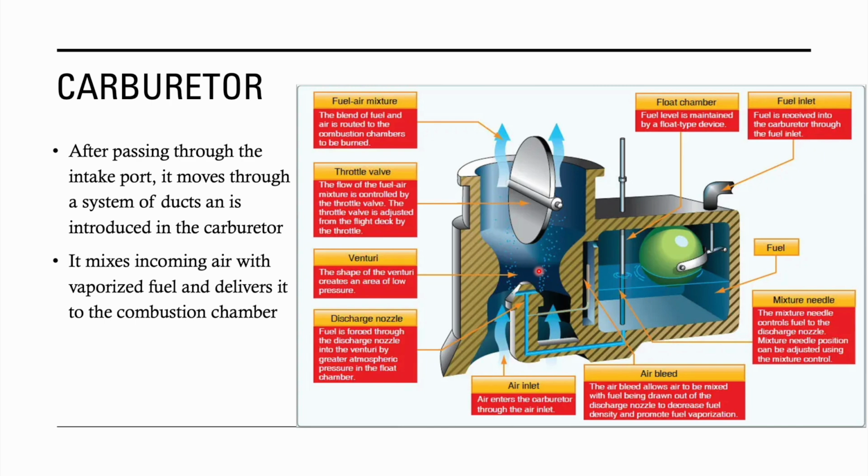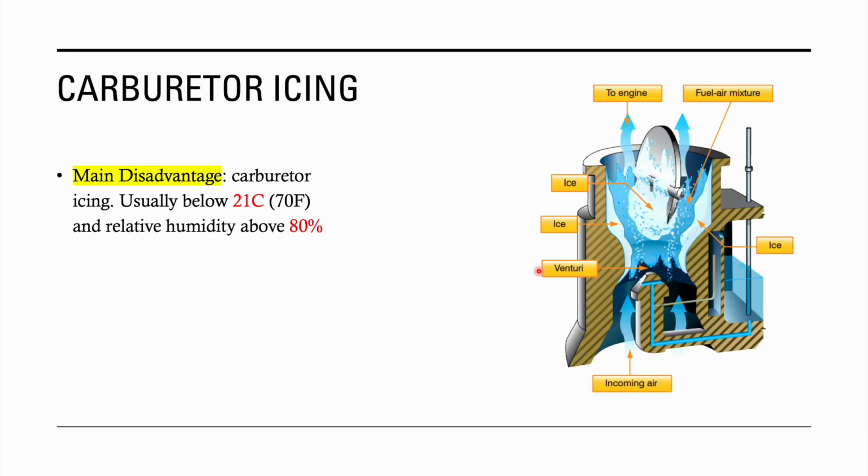It's a very, I would say, reliable design. Carburetor's been around forever, been on motorcycles, cars, airplanes. Major disadvantage would be carburetor icing. Because you experience an increase in velocity and a pressure decrease right here, that also leads to a drop in temperature.